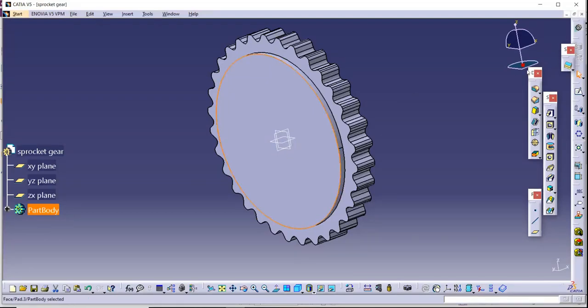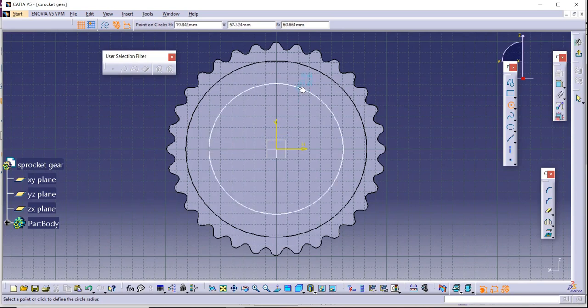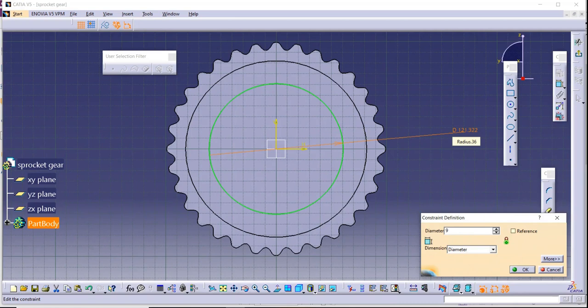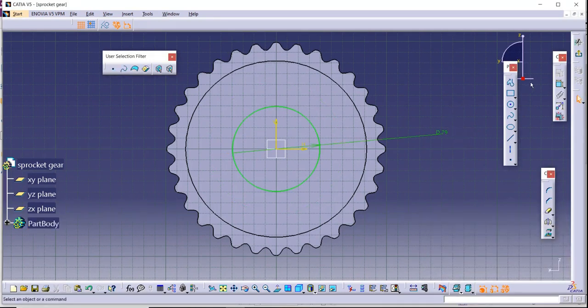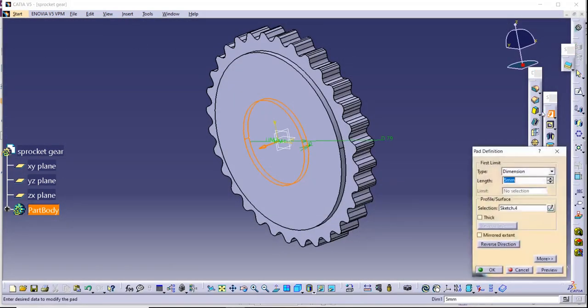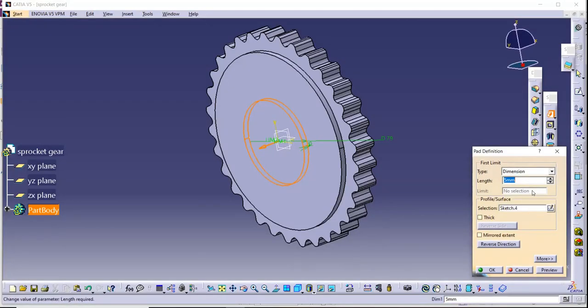Make it from center, 39.5 times 2. It accepts the multiplication in the algorithm. And make it some sort of extrusion on this element. For example, this is around 40. Make it 40.